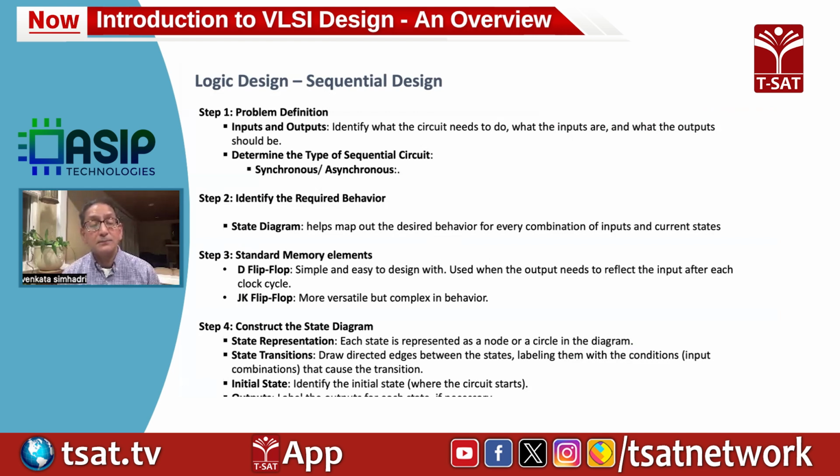You define what are the inputs and outputs, and then you determine whether it's a synchronous design or an asynchronous design. And most SoCs nowadays are all synchronous designs with high-speed clocks in there. Then you identify the required behavior using state diagrams. And then you pick what are the memory elements you use, whether it's a D flip-flop or a JK flip-flop.